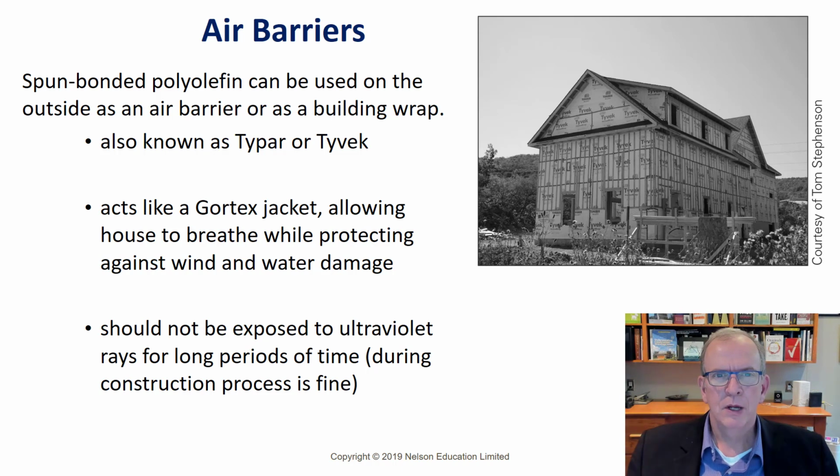It's like we talked about when we did the masonry. That's why you have a 1-inch airspace. If water gets in, you want it to be able to get out. The best systems allow for some problems and still are able to correct themselves. So that's very helpful from that perspective.